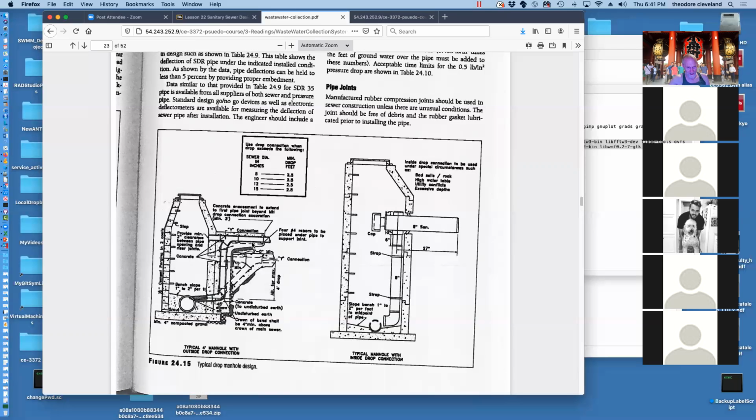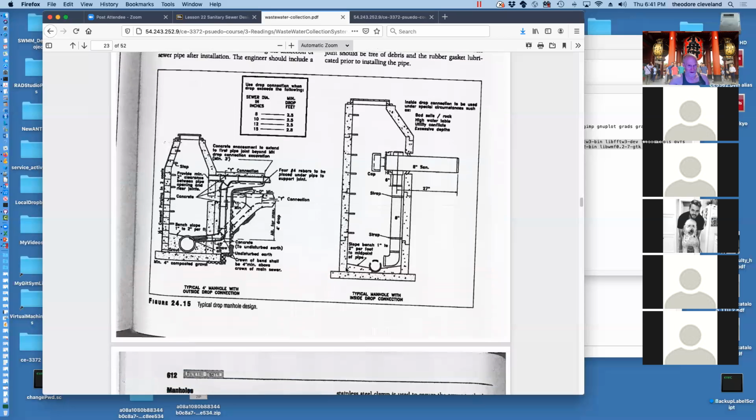And then this detail shows a drop manhole. So the way they're designed is flow is supposed to come this way and drop down this pipe. There's overflow provided. You don't want to physically enter this sewer when this upper pipe is so active that there's overflow coming from the high one. Here's another version of it where it's capped off, but it would still be a provision for excess flows to be able to get in the sewer if these pipes were damaged or blocked.